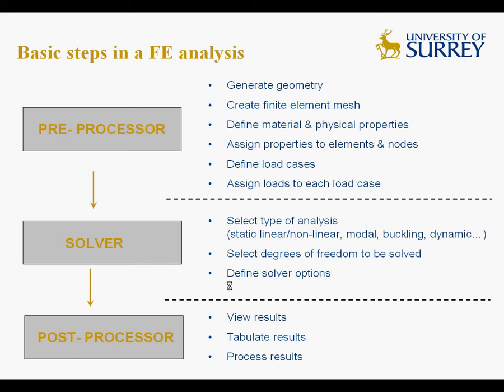Once you finish the preprocessor stage, you can start setting up the solver. First thing is to know the type of analysis you are interested in. For example, if you want to run a simple static linear analysis or a non-linear analysis, if you want to do a modal analysis, buckling or dynamic analysis. You can also select the degrees of freedom you want to solve, or choose the type of elements you want to solve, and also set up some different options for the solver.